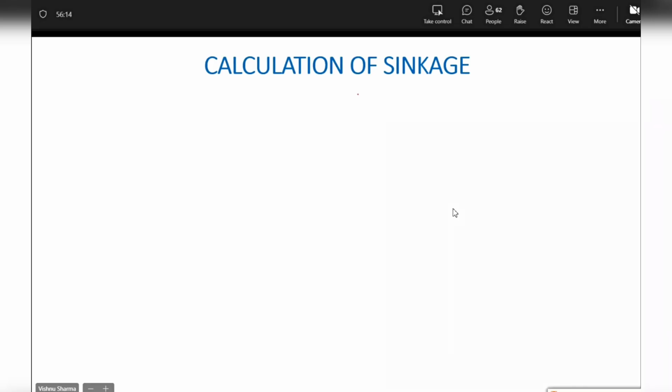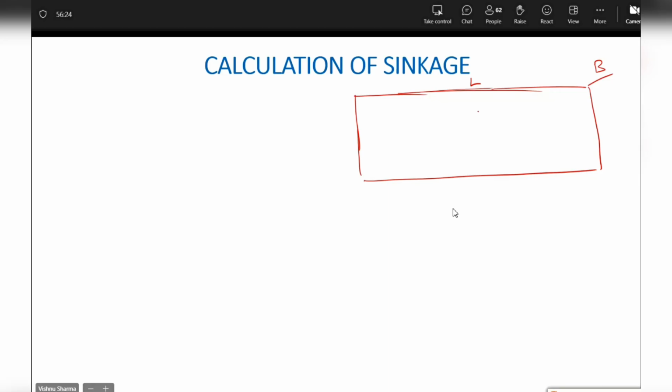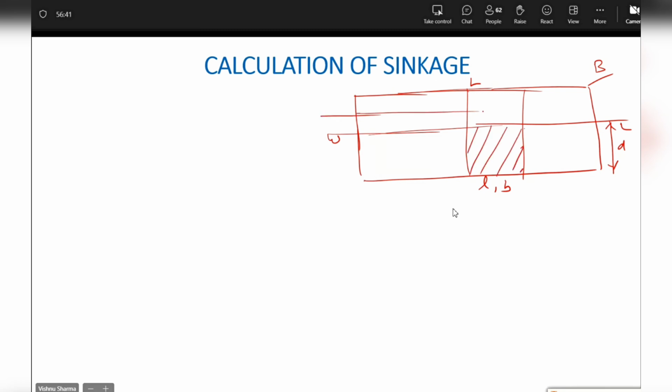Okay, now I make the diagram clearly and now I'll go systematically, guys. The ship has length L, breadth B, floating in intact condition at waterline WL. Every time the same thing we have to repeat. At D, has a midship compartment, small l and small b. It gets bilged. This is the lost buoyancy. Causes the vessel to sink to a new waterline W1L1 with a new draft being D1. This being the sinkage. Okay.